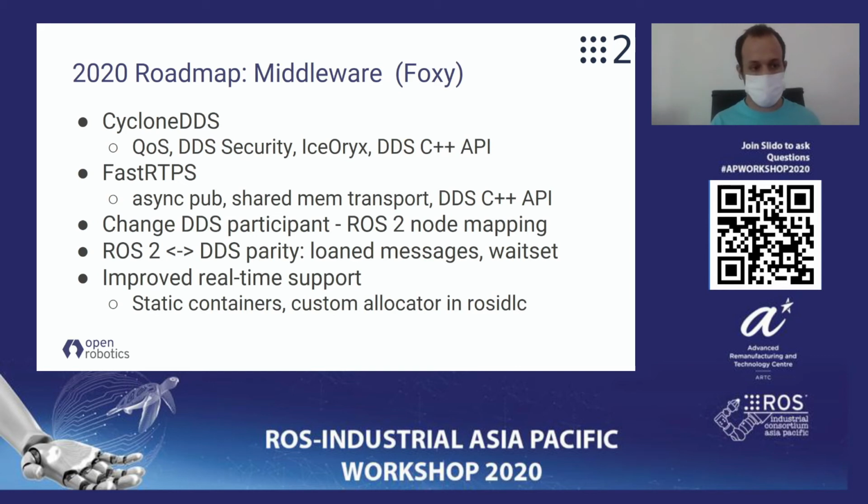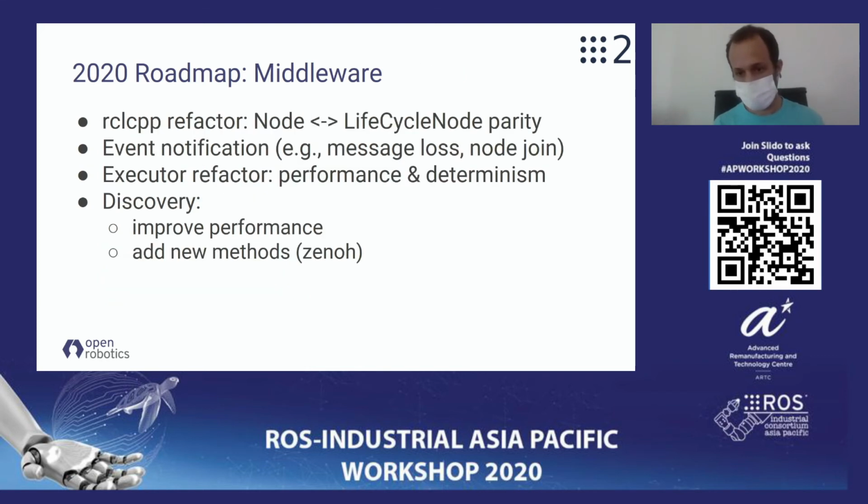There's also a focus to bring ROS2 and DDS to parity with loaned messages and with the wait set, to give the ability to wait on subscriptions without an executor. There's also improved real-time support with static containers and with a custom allocator in ROS IDL. Next.